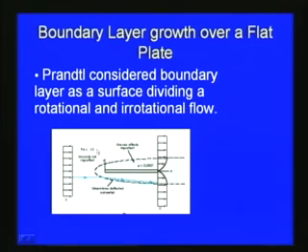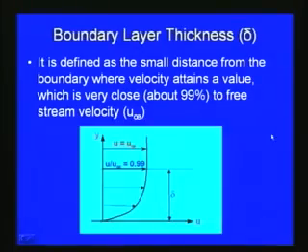So, this is plotted for a Reynolds number of 10 to the power 5, showing how the fluid flow is behaving over a flat plate. Now we will be defining various parameters of the boundary layer like boundary layer thickness, displacement thickness, momentum thickness, energy thickness, so that we can differentiate various parameters with respect to the boundary layer, and further we can try to quantify and derive an expression for the various parameters like velocity and pressure.